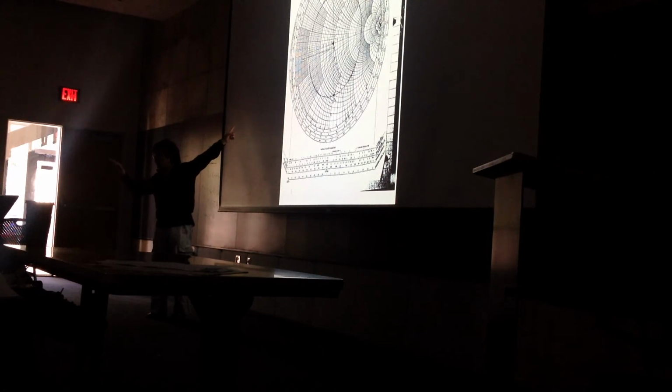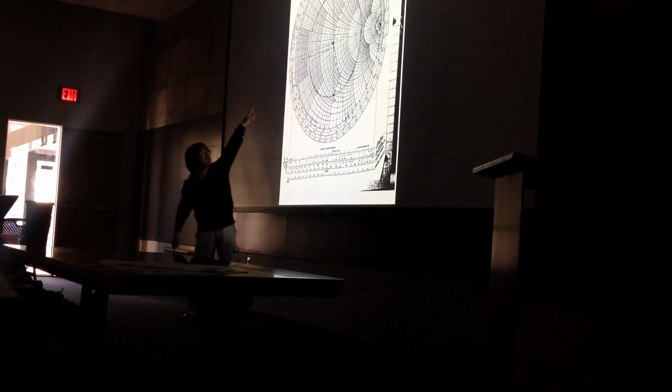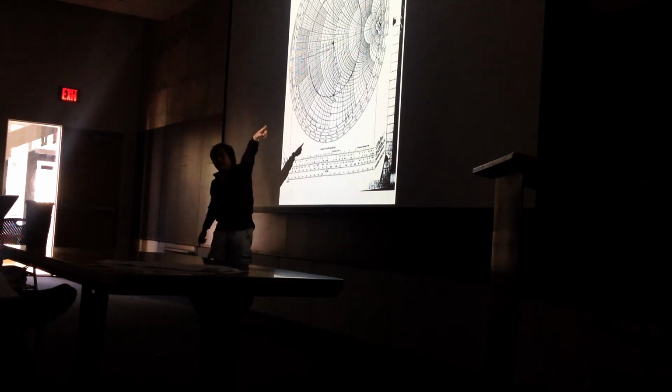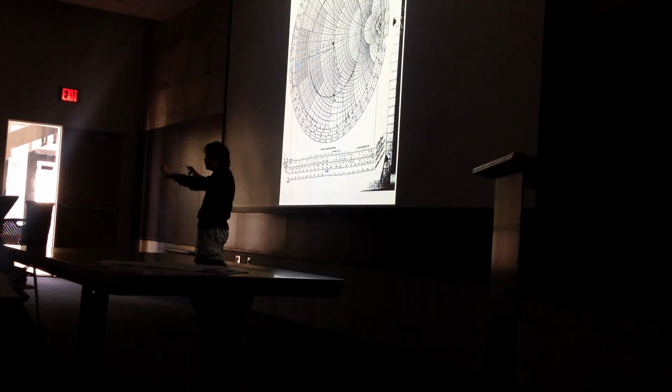So that is impedance. How do I get the admittance? Rotate 180 degrees. So that is the admittance location. So your impedance is equal to 0, your admittance will be infinity. So you take this impedance here, rotate 180 degrees there. So for that transmission line, the reflection coefficient magnitude is always equal to 1.